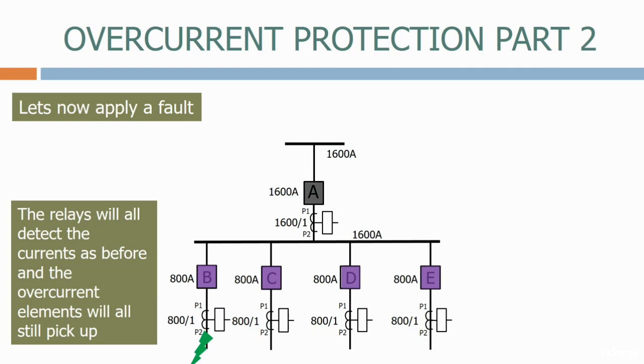The feeder breaker will now operate first, clearing the fault before the time delay on the incomer breaker runs out. But the feeder breakers all trip together, as they are all set to the same time delay, as we have to treat them all the same, as we don't know which one's going to go faulty. Therefore, we still have poor fault discrimination.